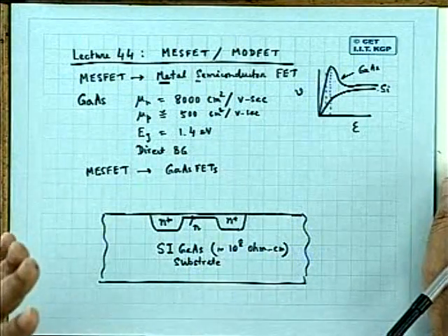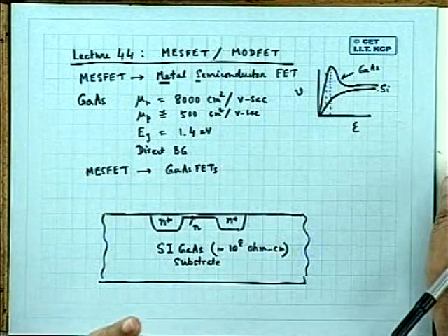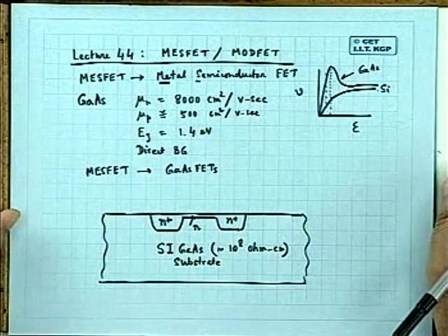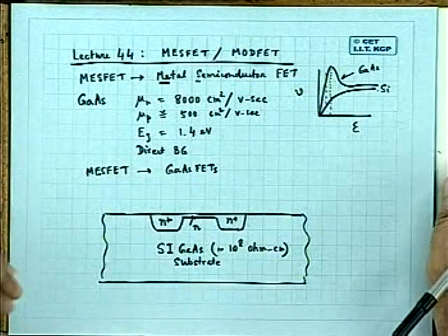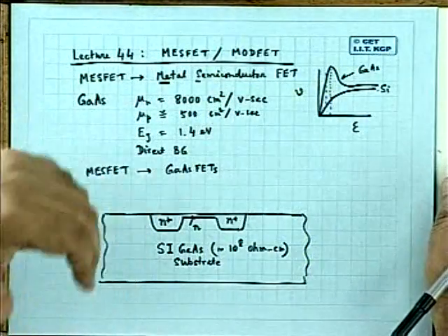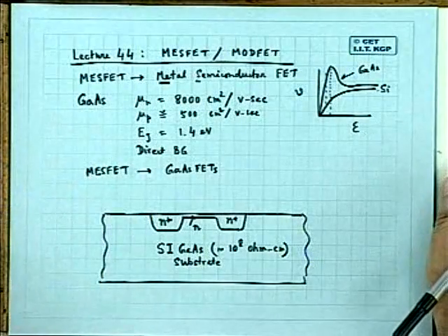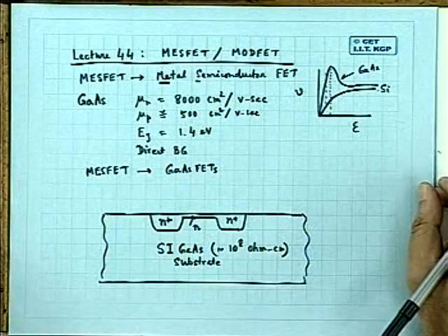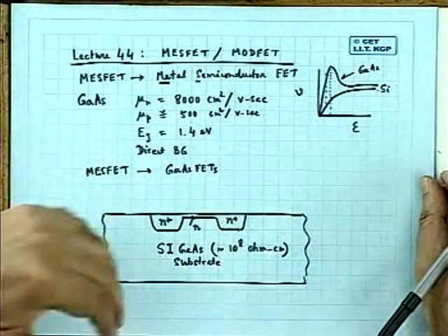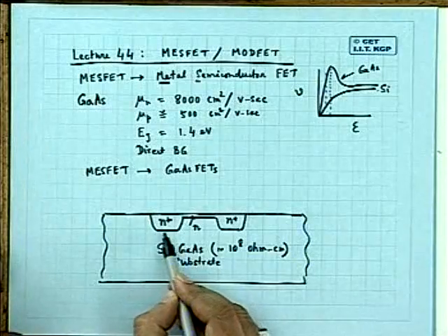If it is doped with a group 6 impurity, it becomes N-type. Silicon is a different thing; it is found to be a very effective N-type impurity for gallium arsenide. Otherwise, selenium, sulfur, etc. were previously used. You implant them, but you have two implantations here.